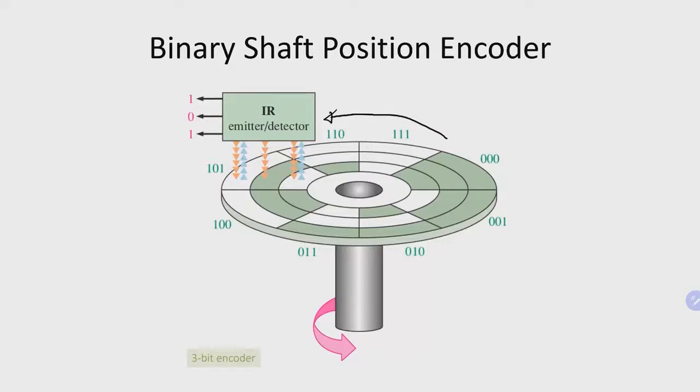If there is misalignment of this detector, so this detector is trying to detect the 3 sectors of the disk. If, let's say, this detector is misaligned, we have it, let's say, from here originally, and then when it is slightly misaligned, it goes from this. Okay, something like that, misalignment. So it's going from 111 to 110 before it gets to 000. So an error occurs, or it might even go to 100 before it goes to 000.